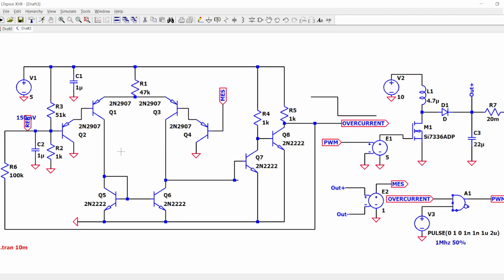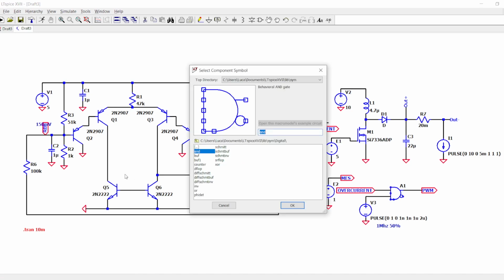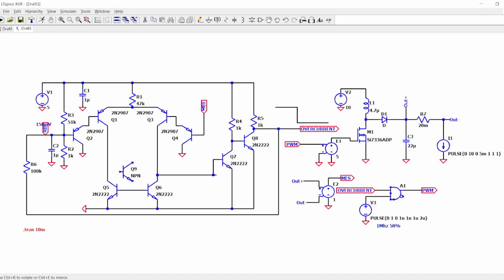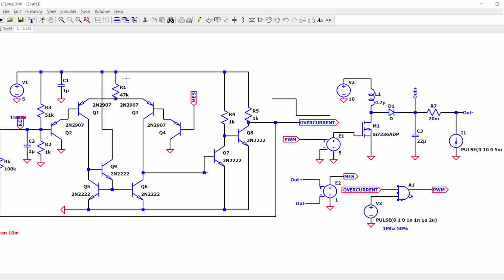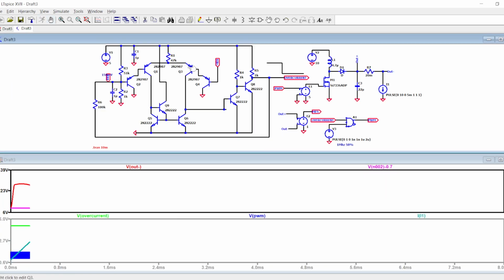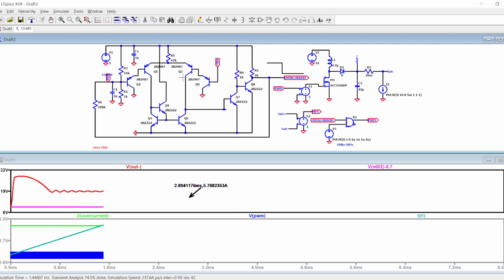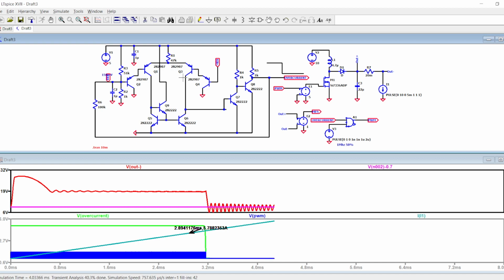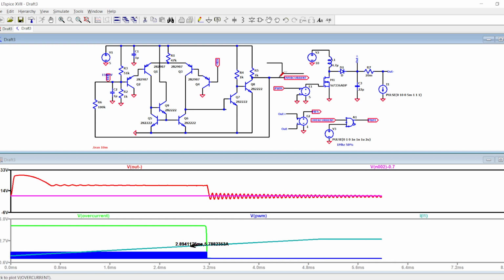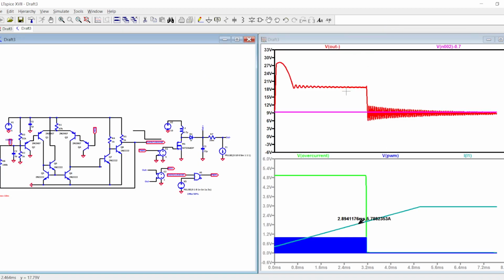You can even improve this circuit by putting another NPN here, which stands like this. This is called the beta helper and improves the performance of your current mirror. Again, I will do a video just for current mirrors. So let me run again the simulation with the beta helper this time. There shouldn't be any kind of differences because the current mirror acts the same. And as you can see, the result is exactly like before.